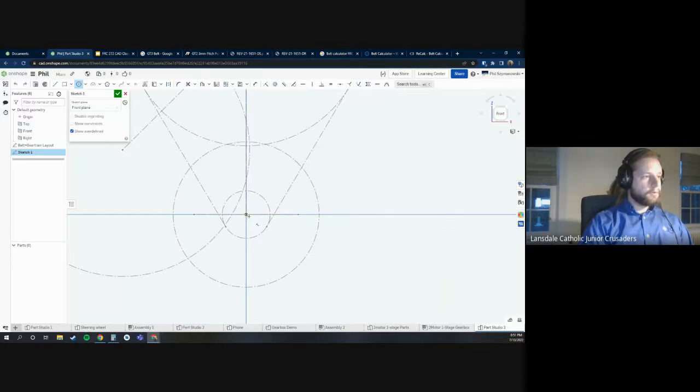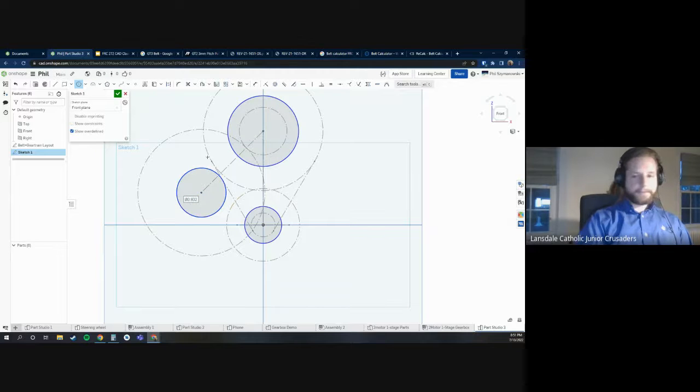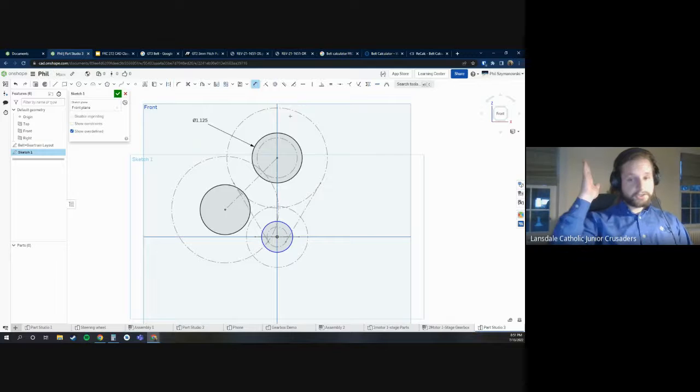So I want to put a hole everywhere where there's going to be any kind of a shaft, like where the motor is and where this shaft is and where this shaft is. And that's just good practice because that's generally where we're going to have bearings. And on these two, I'm going to assume that we're using the same sized bearings, so I'm going to click the equals button. The common bearings that we use are 1 inch and 1/8. These are numbers that I just know off the top of my head because I've designed so many of these gearboxes. But if you don't know this, I would suggest finding the bearing that you're considering using, taking measurements off of it, and plugging those numbers in here.